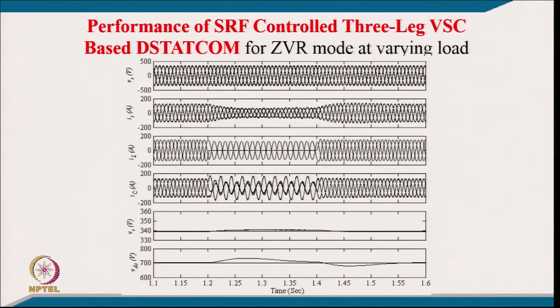and again putting that load current back, so that you look into how the dynamic response is. And this is the compensator or D-STATCOM current. So, if the load is unbalanced, the D-STATCOM current also becomes unbalanced. Otherwise, here it was only compensating the reactive power, because these were lagging loads, and you have to maintain the voltage. So, these are the compensator currents for all three phases, and this is the voltage. You can see the regulated voltage across the point of common coupling. Of course, during dynamics it takes time because of the action of PI control, but it remains regulated.